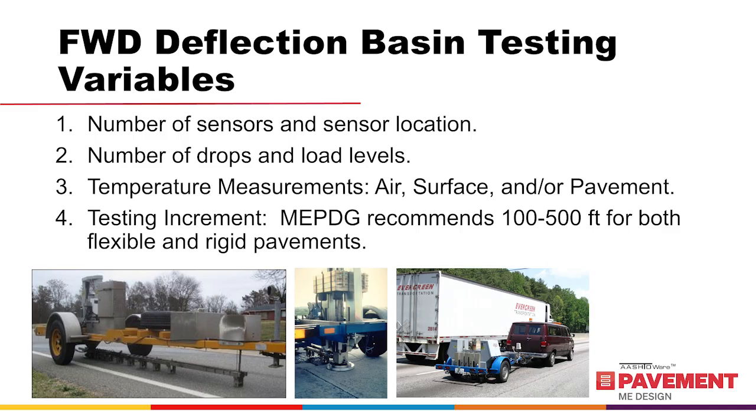ASTM D4964, which is Standard Test Method for Deflections with a Falling Weight Type Impulse Load Device, recommends that at least 2 drops should be performed, whereas the American Association of State Highway and Transportation Officials, which is AASHTO T256, Standard Method of Tests for Pavement Deflection Measurements, and ASTM D4695, which is Standard Guide for General Pavement Deflection Measurements, suggest 1 or more drops at any load level will suffice.